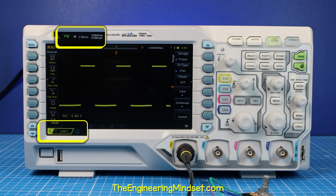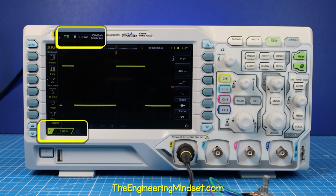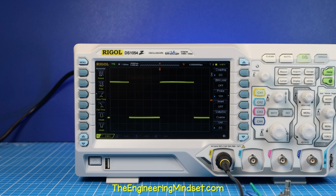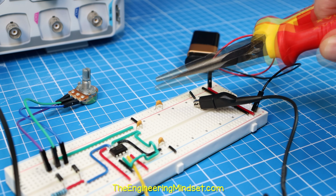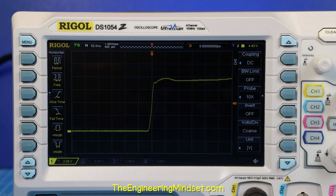Press the auto button and adjust the scales to see the signal, which is a pulse. We can adjust the width of the pulse with the potentiometer. We can zoom in and see the pulse isn't perfect. We can add a capacitor between the positive and ground rail and notice it will improve this.